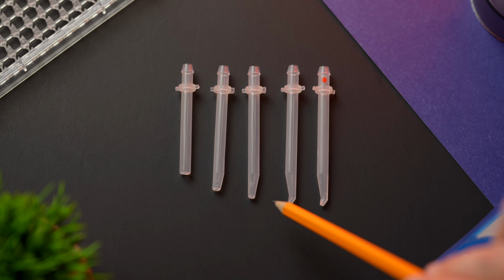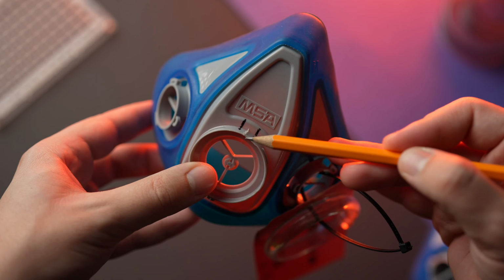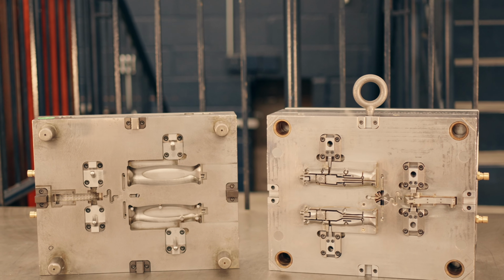And that's because an excessively high filling pressure can lead to short shots, flash, or even mold deflection, which we definitely want to avoid. So early in this design process, you want to confirm that the mold can be filled with normal press limits without pushing the equipment or tooling to its edge.